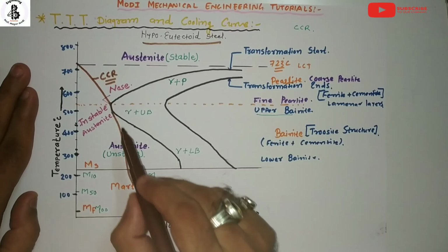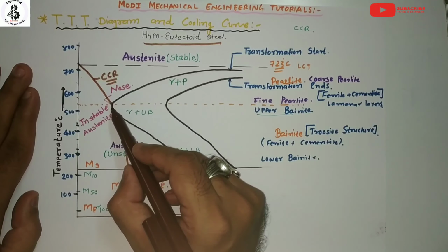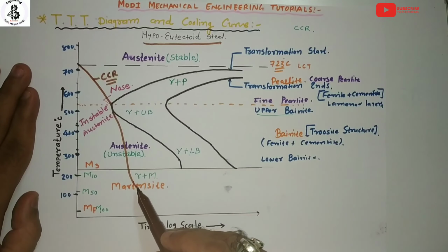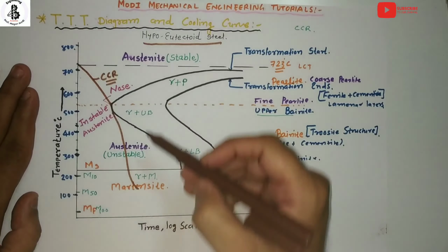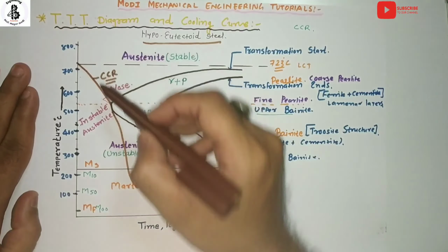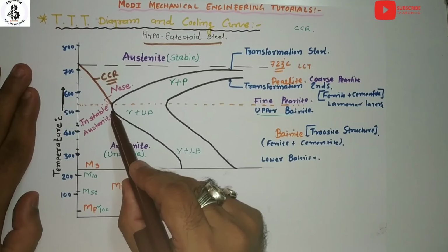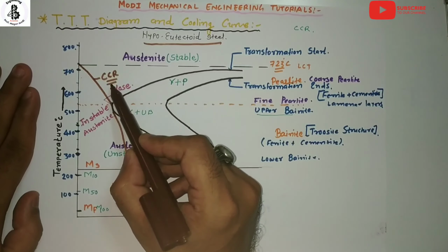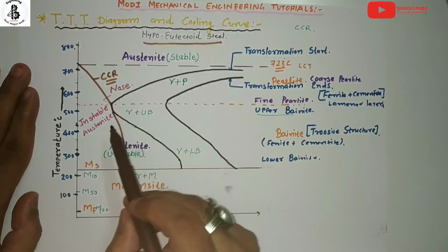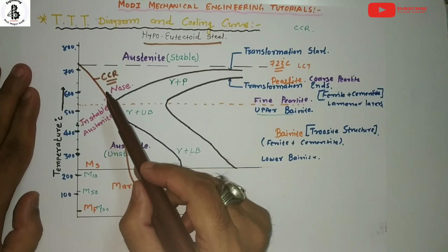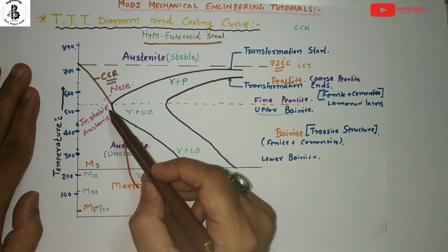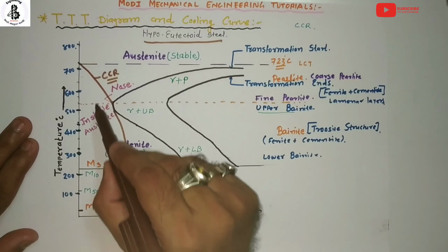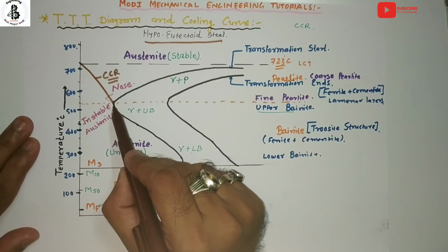As shown in this figure of the TTT diagram for hypoeutectoid steels, the slowest possible cooling rate by which a fully martensite structure can be achieved is possible only if you control the cooling so that it touches the nose of the curve. Such a cooling rate is known as the critical cooling rate, or CCR. Graphically, it is tangential to the nose, or knee, of the TTT curve.